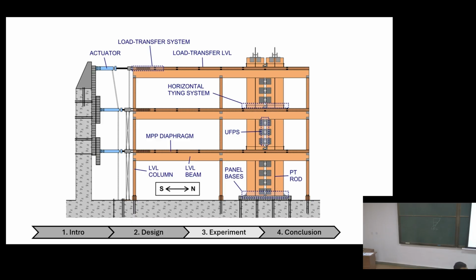Essentially it's a steel bar that goes in and out of the plane of the screen and is welded to the floor with some steel plate, which is bolted to the timber floor. Maybe I have a picture. And that bar, because of its stiffness, transfers the load between the diaphragms and the shear wall. Again, there are no gravity loads coming into the shear wall, and that's one of the requirements of this kind of decoupled lateral and gravity frame system.